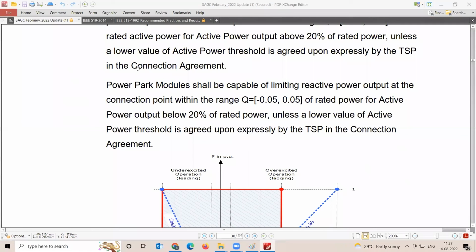But if you are a load, carefully watch my sentence. If you are consuming power from the utility and they are asking you to maintain a power factor of 0.9, they are expecting a minimum power factor of 0.9, which means you have to maintain a power factor of 0.9 and above. If you are a source injecting power to the grid and they are asking you to maintain a power factor of 0.85, your power factor has to be 0.85 or less, which means your reactive power capability is capable of supporting that much reactive power for whatever application is requested by the grid. So the 0.85 or 0.9 power factor of a load has to be proved in the simulation by proving that the power factor is more than that, and the reactive power requirements for sources have to be proved with a power factor less than this, which means being capable of supporting that reactive power.